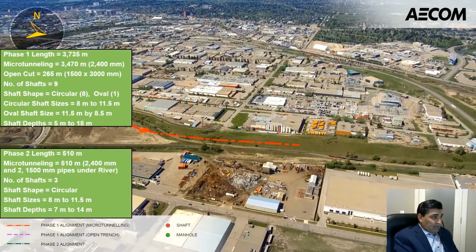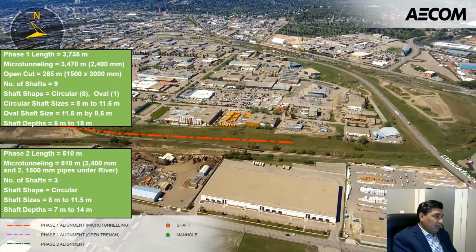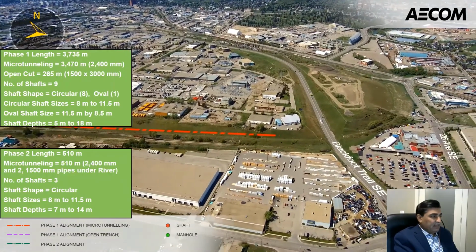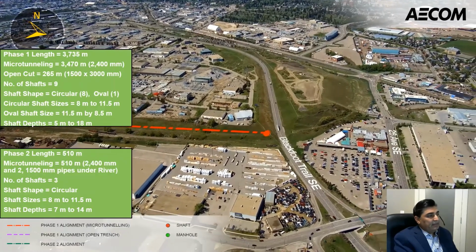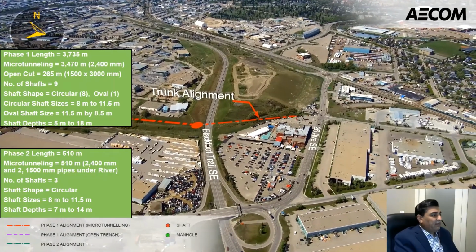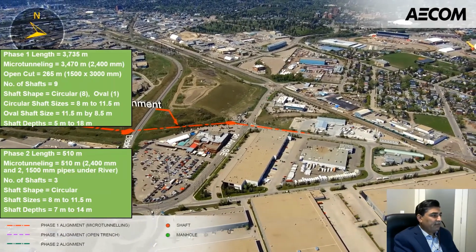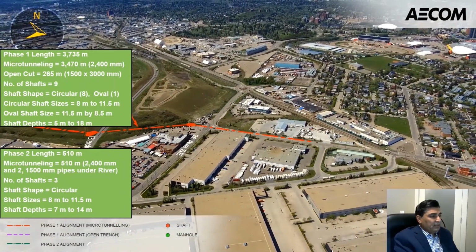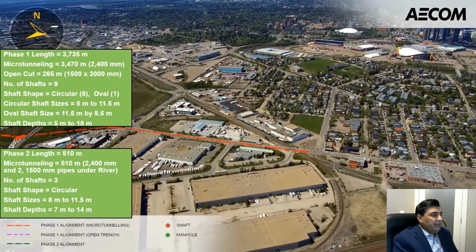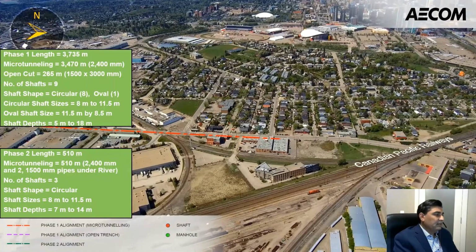There were 9 shafts installed for this project and shaft shapes were mostly circular. 8 of them are circular, 1 of them was oval shaped. Circular shaft sizes varied from 8 meters to 11.5 meters in diameter, and oval shaft size was 11.5 meters by 8.5 meters, and shaft depths varied from 5 meters to 18 meters. You can see the tunnel alignment crosses several railways, major roads, and a major portion of phase 1 was under major roads.